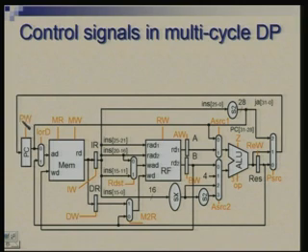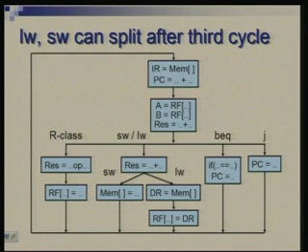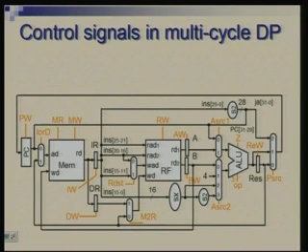So, for PC write I am abbreviating as PW, this is IR write IW, DR write DW, then A and B have their AW and BW signals, and RES write is REW. So, they are control signals which will indicate whether a particular register changes its state in a cycle or not. And in which cycle the state is changed, we will know from this flow chart. So, we will always refer to this flow chart or state transition diagram and then decide the values.